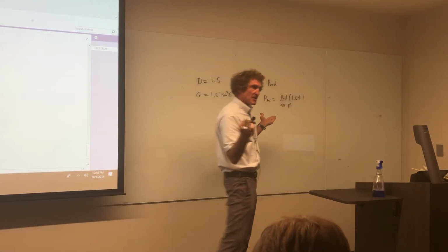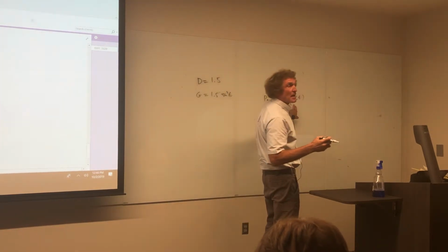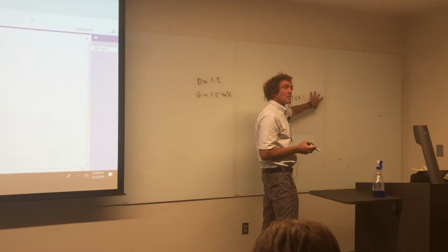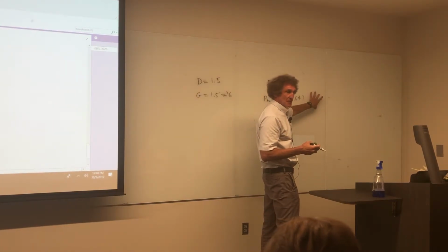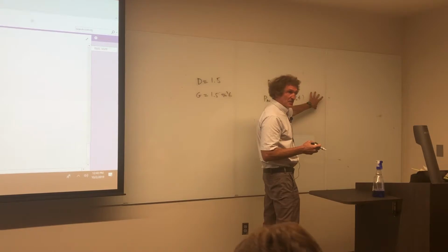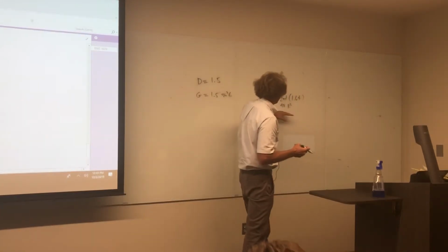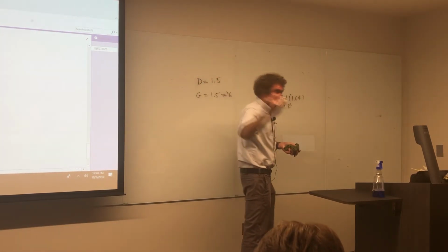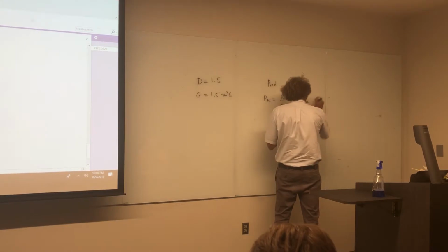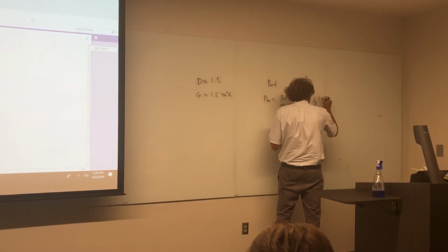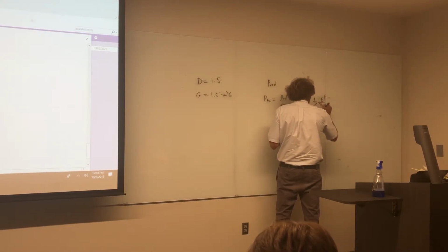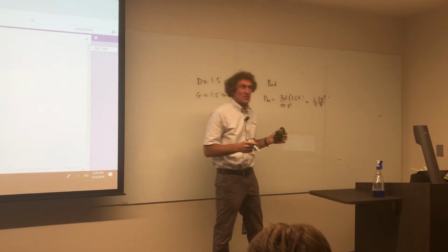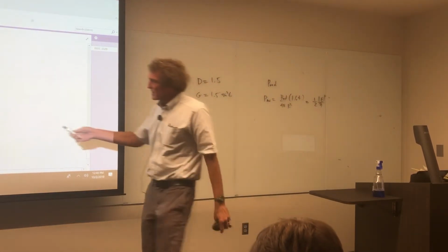You had problems on this, several. Now that's that, and you know that there would be times f of theta, but there I asked at 90 degrees, right? Correct, class? So at 90, that's 1, and that's something we covered in class. So that'll give you the average power density at that point, and the average power density is equal to 1/2 magnitude of the E field squared over eta, right? So you can get the E field. I think I did it that way here.